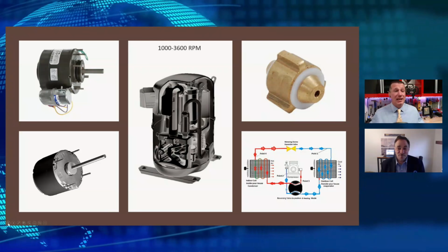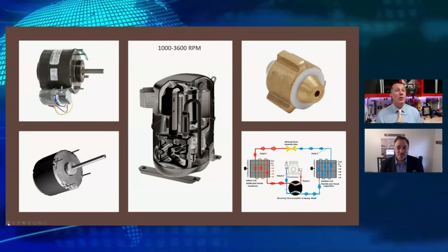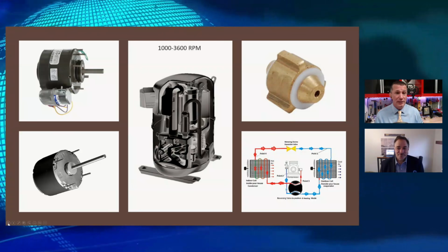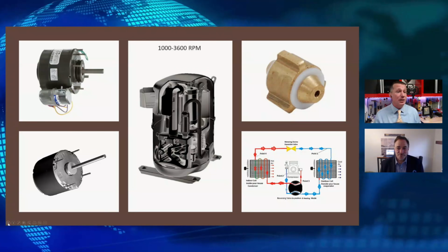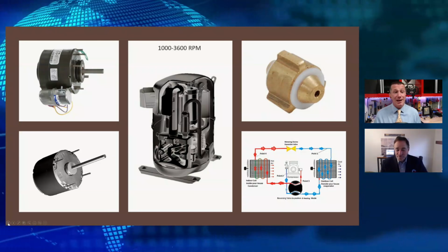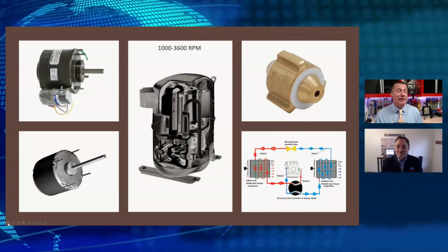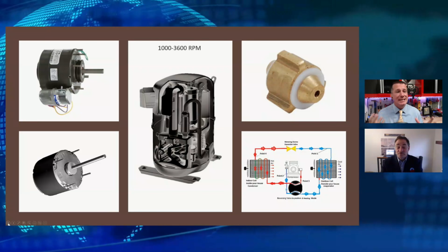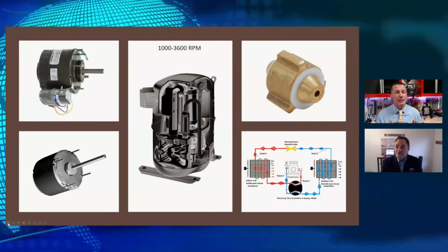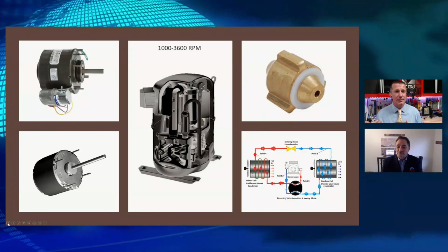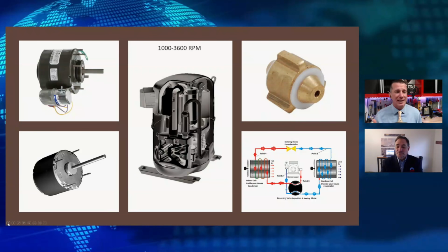Are we going to see inverter systems out there that are inexpensive? Yes. Are we going to see inverter systems that are not truly variable speed on all the components? Yes. Are we going to see inverters that don't have electronic expansion valves, therefore cannot be capable of running at ultra low temperatures? Yes. A lot to interpret, and that's why we need our tools. We need to be able to compare different pieces of equipment to see what the capability is, put some high quality manufacturing to it, and then get the data that proves exactly how those things operate.